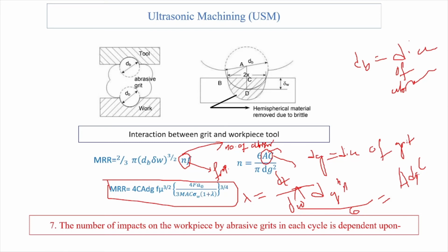One more thing: the basic mechanical structure of USM is very similar to a drill press itself. However, it has additional features to carry out USM of brittle materials. The workpiece is mounted on a vise, which can be located at the desired position under the tool using a 2-axis table. The table can be lowered or raised to accommodate work of different thickness.